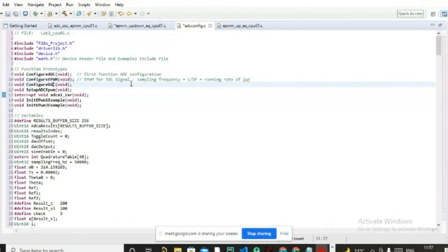Then you have DAC. Okay, so this is to configure your DAC, and in order to see the analog to digital signal that you have converted, whether the same signal you are getting into the board or not, for that you can use DAC. Like let's say you have a signal inside and you want to see it on the oscilloscope, whether the same signal is there or not. That digital data you can convert into analog form, and you can see the output on your oscilloscope. So whatever signal you are converting, whether it is accurate or not, you can detect with the help of DAC. We'll see how to do the setting for that DAC as well. There are other registers, and I did not want to confuse you with ADC, so I'll take it later.